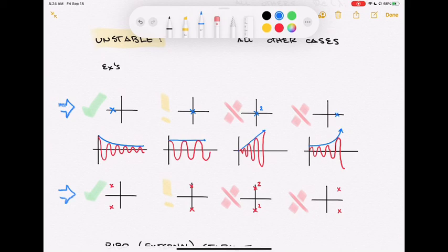Let's take a look at the first diagram that I gave. That's this one sitting over here, where I have a single real root off in the left half plane. We'd already kind of got a hint on that. That might be like -1. That gives us a decaying exponential, e to the minus t. That's that line in blue directly beneath the graph, right? So we get that curve going down in an exponential way. Nice and stable system. That's why I put the green check over there, because you stuff energy into the system and it bleeds that energy away and heads off to zero.